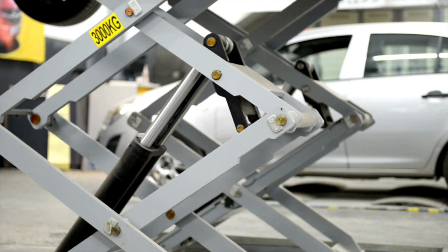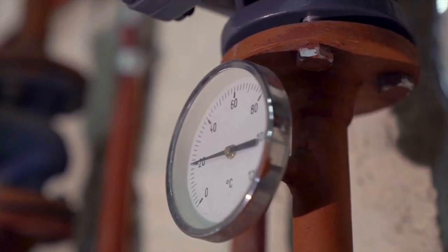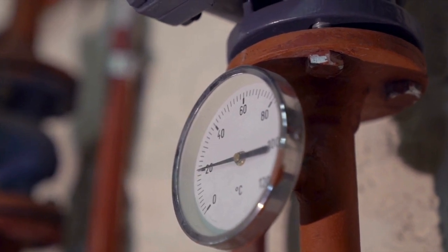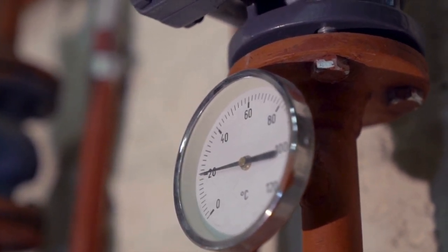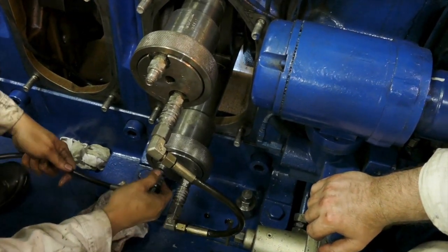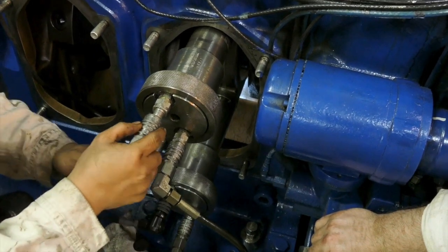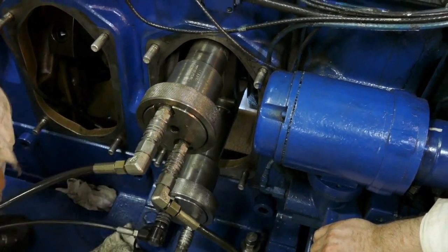Hydraulic and pneumatic energy can result in sudden releases or leaks, posing a risk of injury to workers. To mitigate these risks, workers should depressurize systems and use blocking devices to prevent unexpected movement. Regular inspections and maintenance can help identify and address potential hazards before they cause harm.